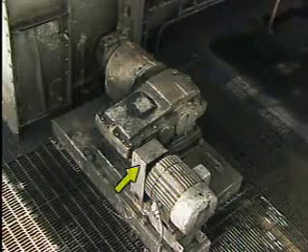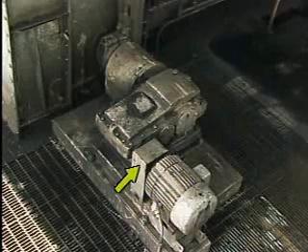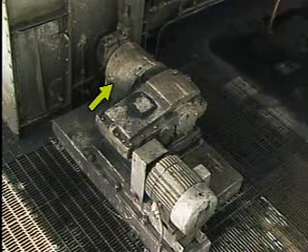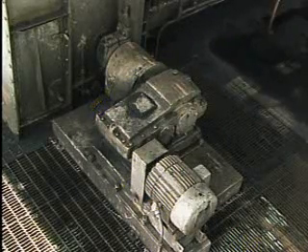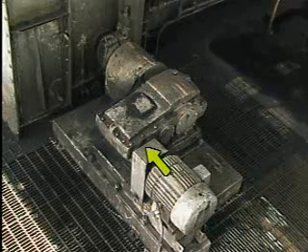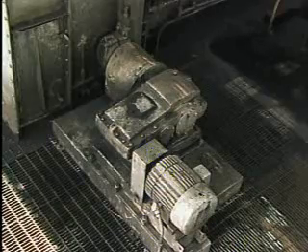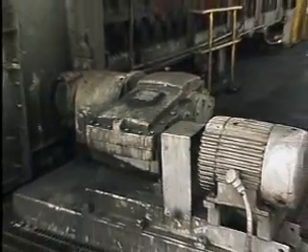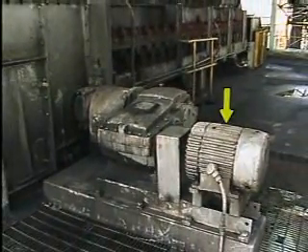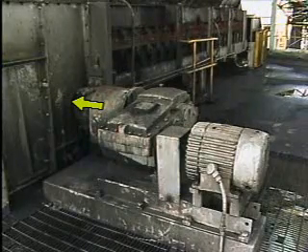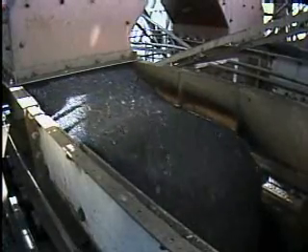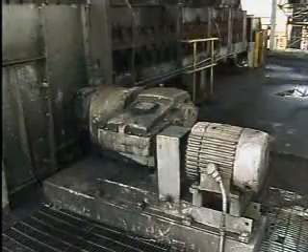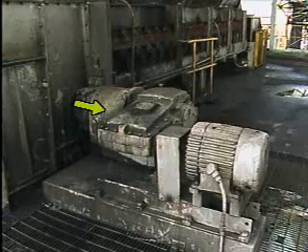The malfunction of either the couplings between the gearbox and the prime mover or those between the gearbox and the driven equipment could be the cause of bearing failure. A failed coupling could cause excessive vibration to be transmitted to the gearbox and bearings. A failed coupling could also throw a gearbox shaft out of alignment. Still another reason for bearings to fail could be that either the prime mover or the equipment that's supplied by the gearbox is operating improperly. For example, a conveyor belt could be periodically overloaded during operation. This overload may be transmitted to the bearings in the gearbox and could damage them.